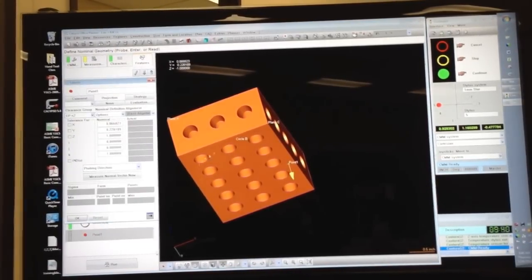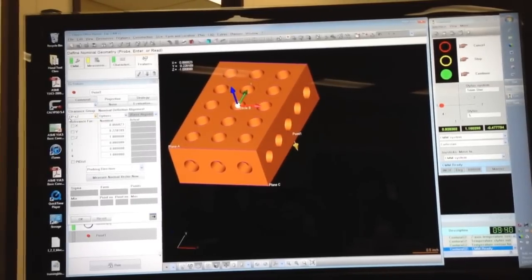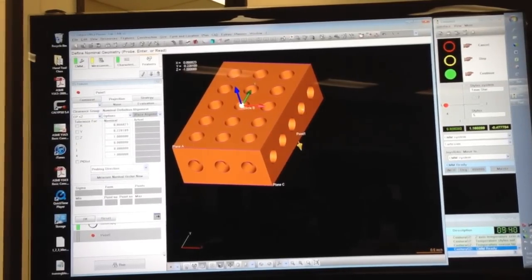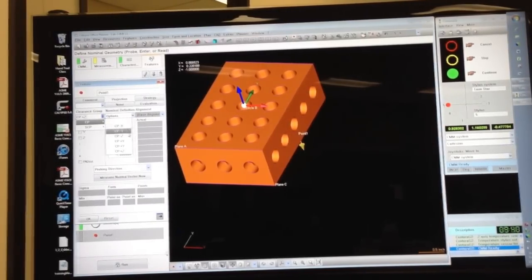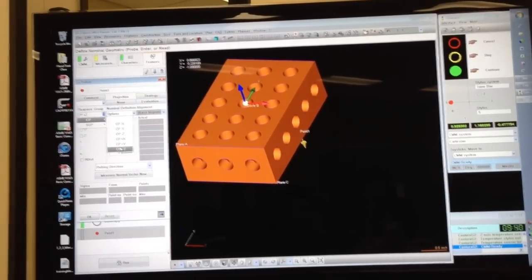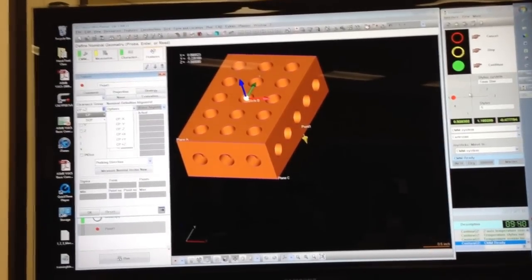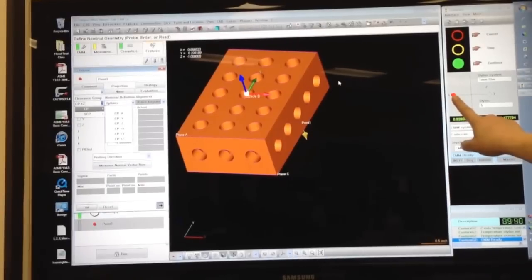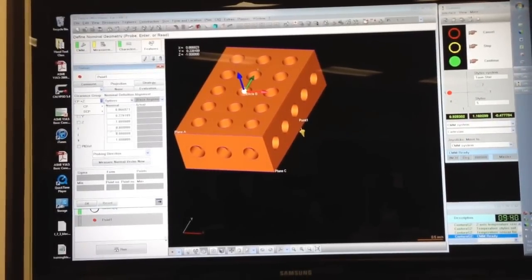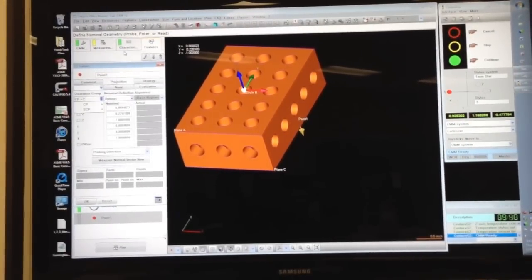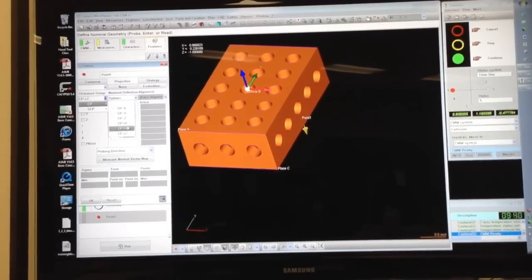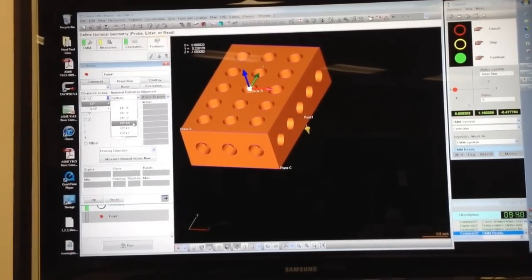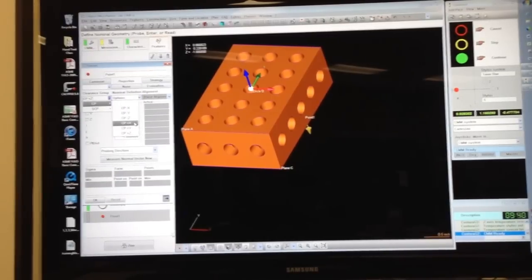For this point, you'll see that it came in with a clearance plane of +Z, but I cannot go straight through the part to this point. So I have to adjust the clearance group to +X. One of the things to remember in Calypso is that when I'm using the negative x stylus, I should almost always use the positive x clearance plane. Paired opposites. Minus z stylus, plus z clearance plane. Minus y stylus, plus y clearance plane.